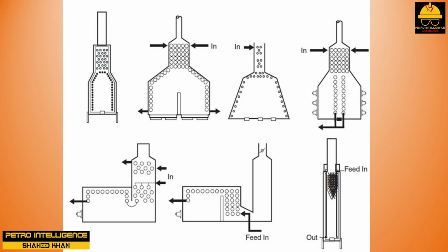However, there are reformer furnaces in which steam and methane are reacted together to get synthesis gas, carbon monoxide and hydrogen. For the catalytic cracking of hydrocarbons, catalytic pellets are packed in the tubes inside the furnace. Notice that the raw material feed to the furnace is preheated by introducing the feed into the furnace through tubes in the vented stack. The hot vent gases heat the feed before it reaches the tubes, which are in direct contact with the flames of the burning fuel gas. Reaction furnaces are used in the olefins and vinyl chloride unit.